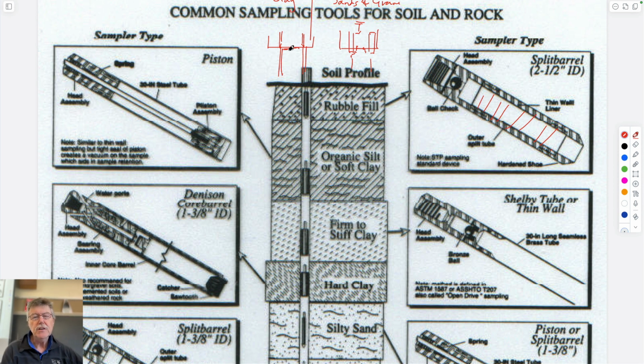And so the idea here is not so much in clays, but in silts. This plunger, it's like a syringe, is right in the bottom of the hole. And so now when you twist it to break it off at the bottom and then retract it, if you don't have something that can provide suction at this interface here, so it pulls the sample back out, it will just wash out. You don't need a check valve as you do for sand. But if you don't have something to suck it up, then it will tend to stay in the ground and just allow the tube to come up empty.